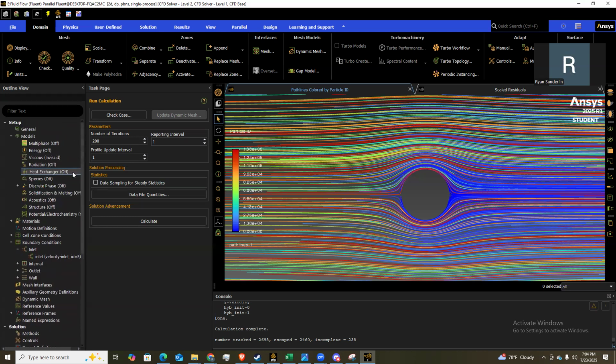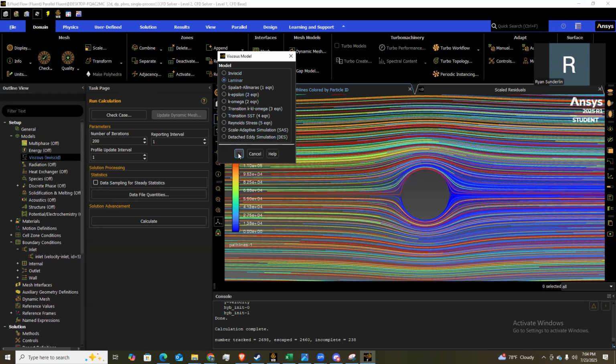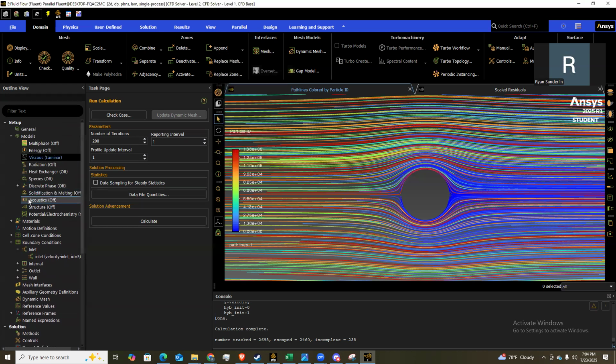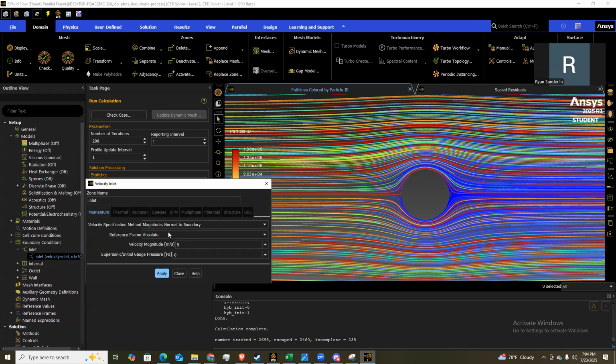So now that I've got that, we can swap over to the laminar case. For the laminar case, we are going to set the Reynolds number to less than the critical number, which is 500,000, because this is an external flow. So we'll go here to the inlet, set the velocity to 2.